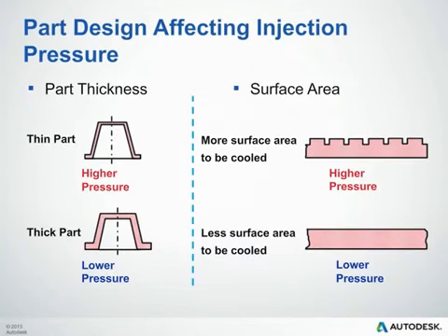Our part design will affect injection pressure as well. So part thickness, you can see on the left, we have a thin part at the top that's going to have a higher pressure. The thicker part we can assume will have a lower pressure.